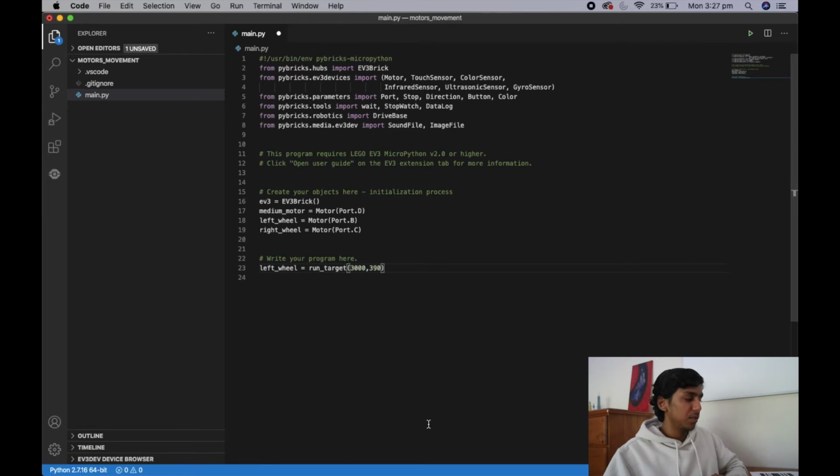Now, in the future, just in a couple of minutes, we'll explain how to make a 2-wheel turn. So a 1-wheel turn is where one wheel is moving forward and the other one is stationary. Now this is going to be a 1-wheel turn. To make a 2-wheel turn, what we're going to need to do is turn one wheel forward and one wheel backwards. This is going to be a turn on the spot, however, we'll get to that soon. So let's see what this looks like.